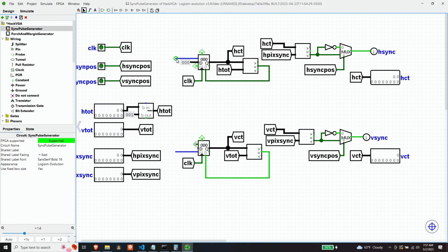Well, the logical way, and the way that I had it, was that you would increment the counter at such point that the carry is true. However, the carry is true only instantaneously because of the way this is wired up, which is not enough time to increment this counter, which happens synchronously with the clock.